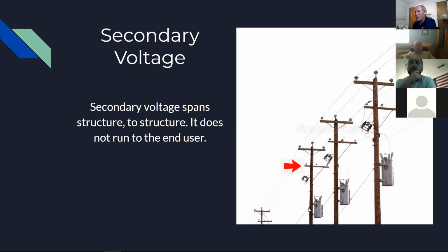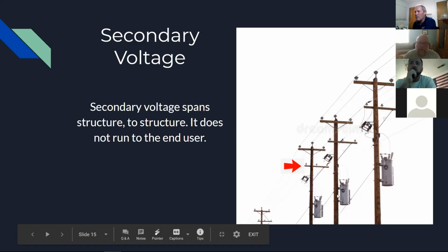But I'd like to talk about this picture just a little bit. What are these? Regulators. Yeah, whoever said regulators is right on the spot. Because there's different fashions, and you'll see these driving around. I don't have to have all my regulators in one platform bank. I don't have to have them in a substation. I can actually separate them out and put them on 3 different poles. So those are 3 voltage regulators installed on 3 poles.